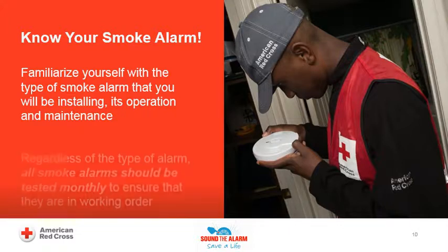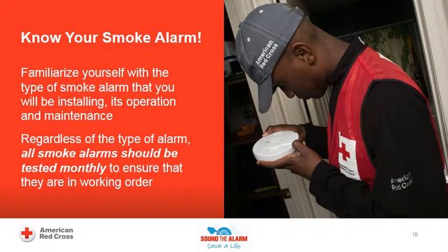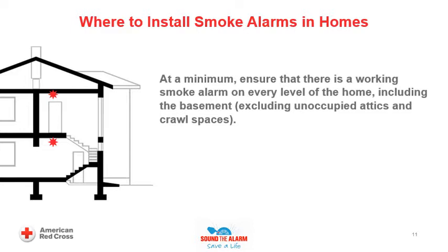Remember, regardless of whether an alarm is hardwired, 10-year or 9-volt, all smoke alarms should be tested monthly to ensure that they are in working order. All smoke alarms should be replaced after 10 years or earlier if needed. This includes hardwired units. Where to install smoke alarms in homes? At a minimum, ensure that there is a working smoke alarm on every level of the home, including the basement, excluding unoccupied attics and crawl spaces.